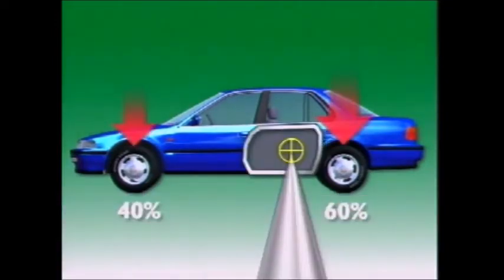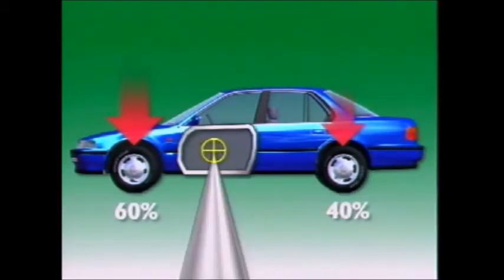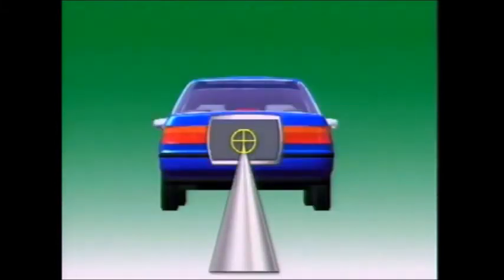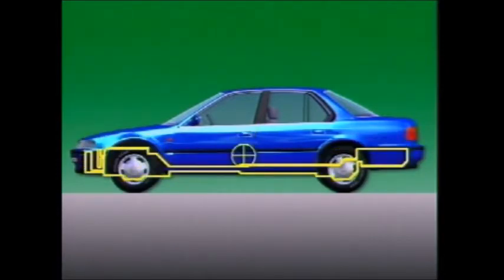This is a 40%, 60% fore and aft weight distribution. 40% of the weight is carried on the front wheels, 60% on the rear, and the centre of gravity is closer to the rear than the front. A weight distribution of 60-40 has the centre of gravity closer to the front than the rear. Lateral weight distribution can be expressed in the same way. The height of the centre of gravity is determined by the height of the mass above the road surface.